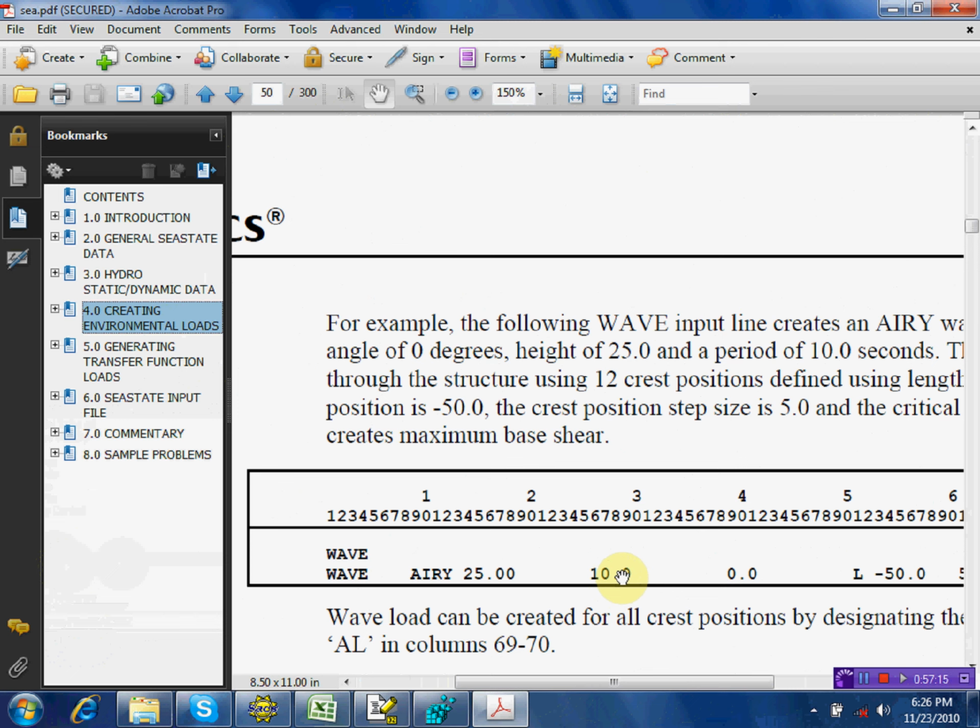The principle is the same. It's load out, top, jacket. It depends on the installation procedure. For example, top side can also be done by skidding. Have you performed skidding of the top side before? In future, if it's heavy, you cannot lift it. You have to skid. You provide skid shoe.